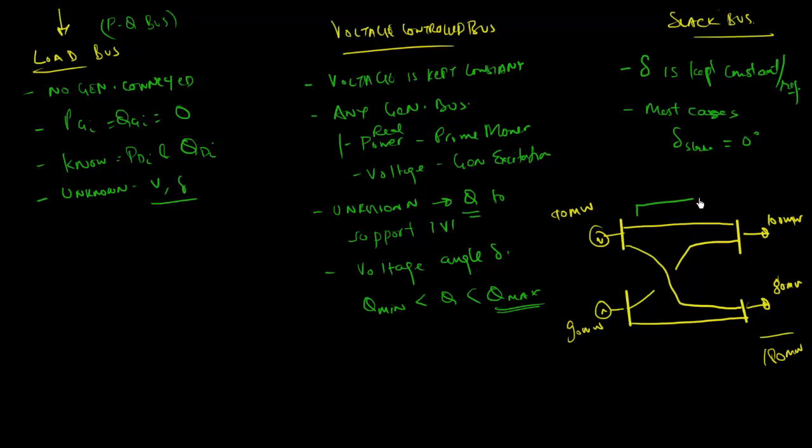We will not know what the losses in these transmission lines are till you have all the voltages and all the power flow. So basically you have the result of your power flow solution. Once you have that solution, then you know the current through each of these transmission lines. You can find out your I square R losses. Let's say the loss in the system is 20 megawatts.